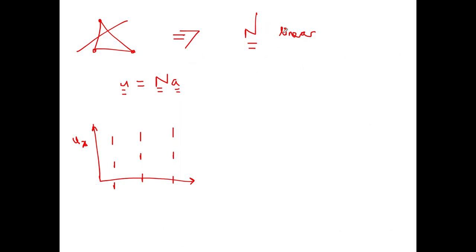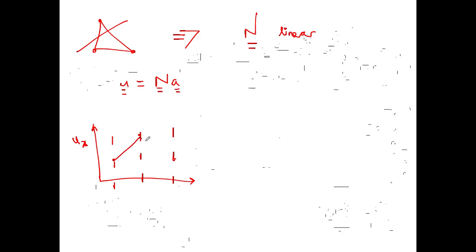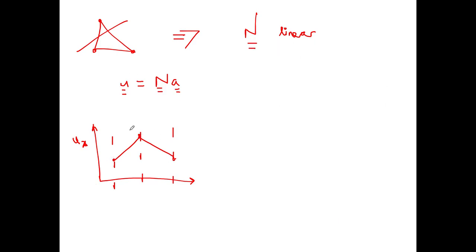Then my linear shape functions will lead to a linearly interpolating displacement profile, where the displacement profile, the essential variable, will be continuous over the boundaries. That is, these are C0 continuous elements. And even if I use quadrilateral elements, then even then the essential variable will be continuous, but I have to use isoparametric mapping for that.